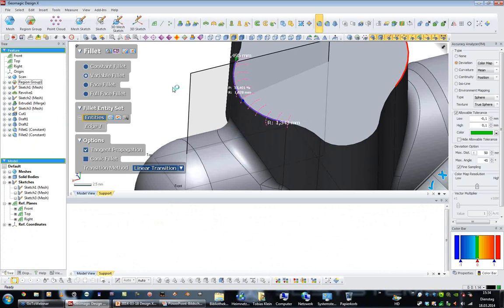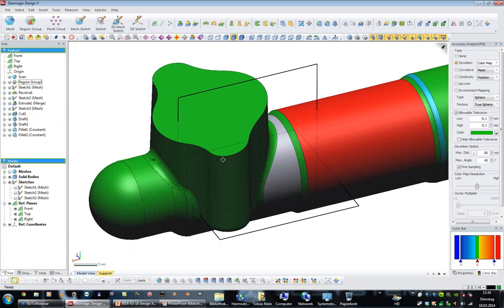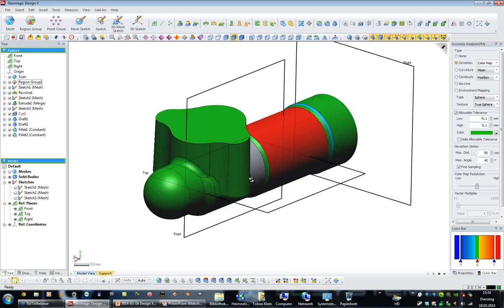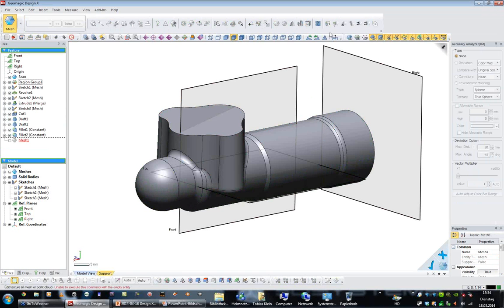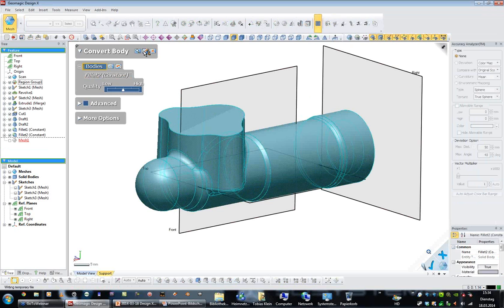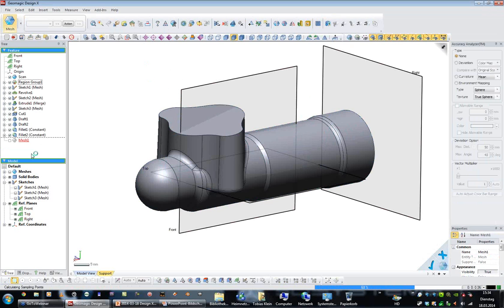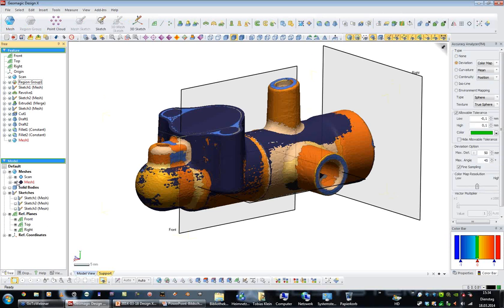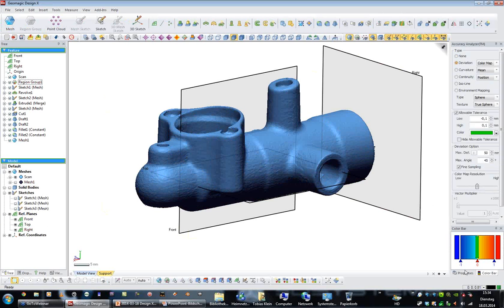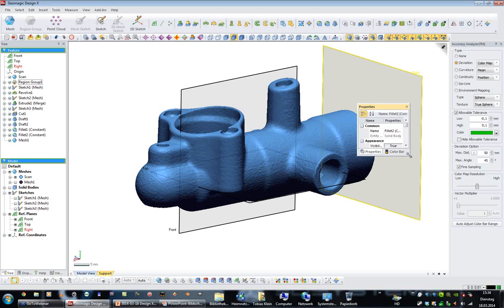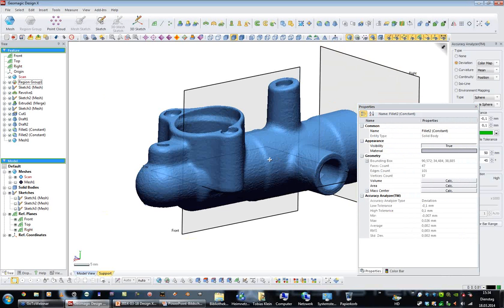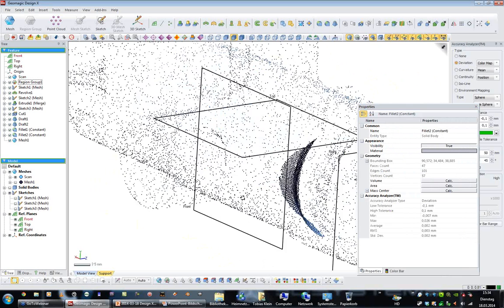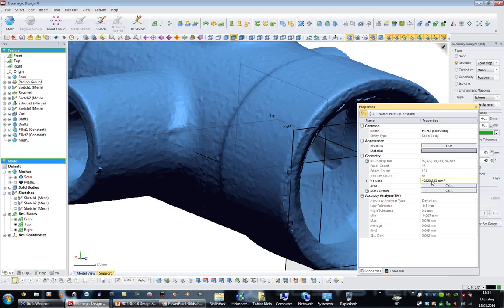Okay. How can I check whether a design is printable or generally manufacturable? Okay, the design as it is is not yet printable, but we can generate a mesh from it. We just convert this body back to a mesh, and the mesh itself is of course printable. So we can compare that with the original mesh. Let's see the original scan, and we have the properties here. In the properties, as you could see in the beginning, the scan is incomplete. It has holes, it has some small defects and everything, and you can calculate the volume here.